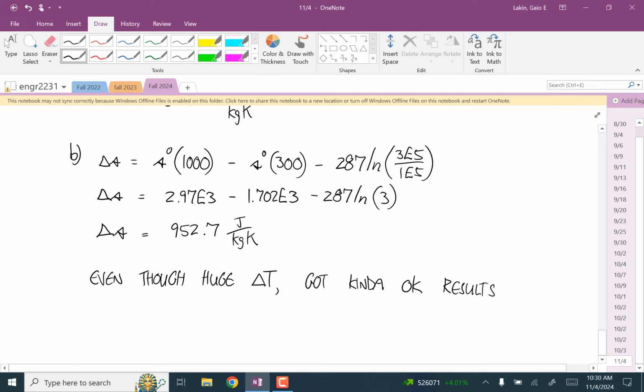And so in the real world, if you were trying to calculate something to design a system and you have limited information, would you just take that 850-ish or 890 number and say, okay, I'm going to make it able to withstand 1,000? I think it just always comes down to how much precision you need for your calculation. You just need to keep in the back of your mind that this is a useful approximation over a big range of temperatures. But the bigger the temperature range is, the less I want to trust that value. That's all.